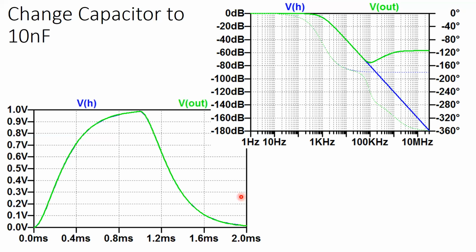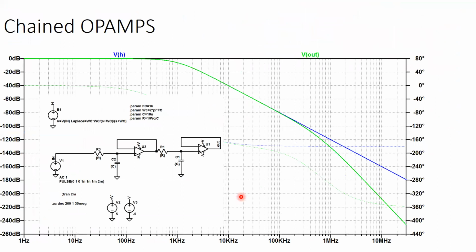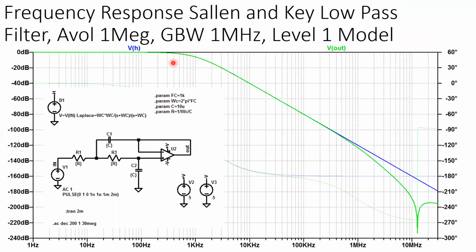and the frequency response, while it worked, never matched theory, right? Not only that, I didn't do a formal Bode plot. I'm just looking at the oscilloscope and changing the frequency and trying to find, in this case, the minus 60 dB point, and it's not showing up where it should. Like, that's okay. Maybe my capacitors are 10% off. Maybe these are off. So I calculate it. Doesn't explain it. It's way off.